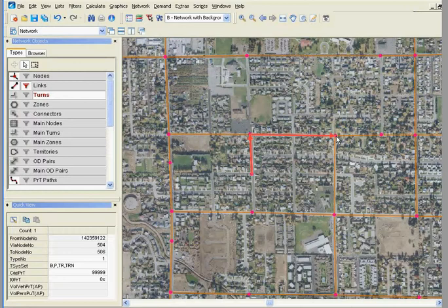Zones, often referred to as transportation analysis zones, represent the origin and destination geography for trip ends in the model domain. The OD, or demand data, is linked with the zone. Also, user-definable attribute information for activities such as the land use data used for trip generation is stored in a zone network object. Zones may be created using the network editor or imported from shapefiles.